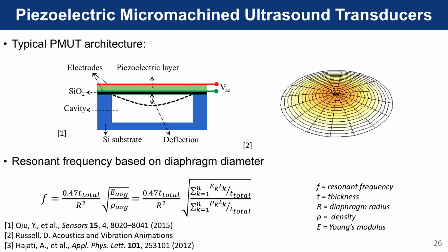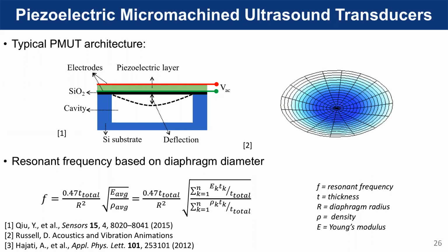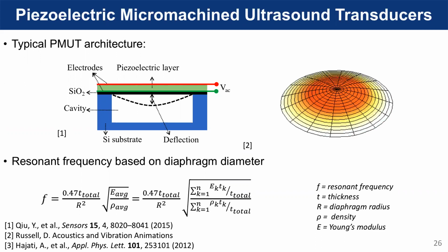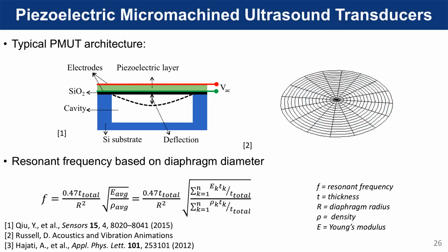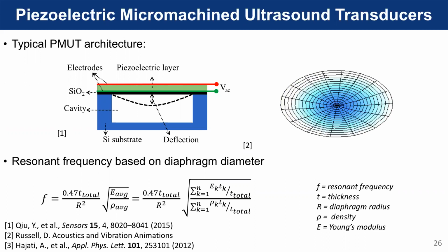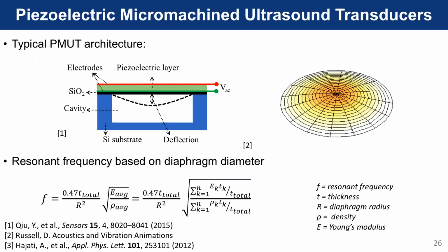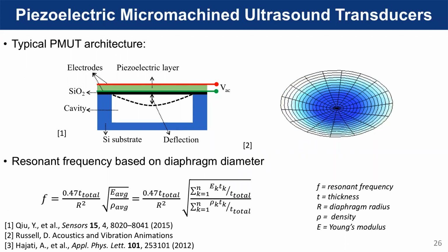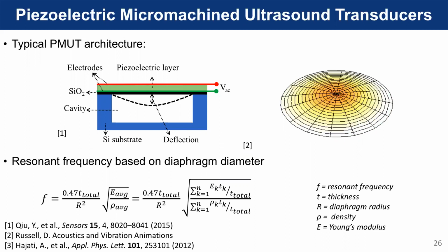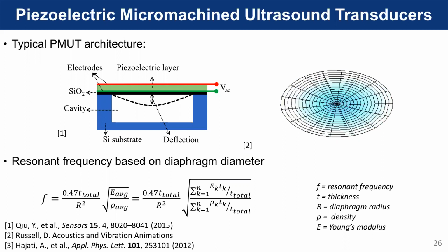The devices you find in a current doctor's office are piezoelectric bulk materials, which have been subdivided into individual elements by diamond sawing. Typically, those devices are actuated at 60 to 100 volts. And it would be very, very useful to be able to decrease the operating voltage of these devices by simply decreasing the thickness of the functional piezoelectric. That allows us to get large absolute electric fields at small absolute voltages.